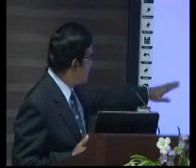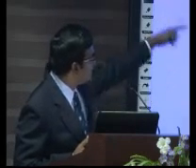What are the components in a skeleton bridge abutment? It has a base slab, with tapered columns on top of the base slab. Then you have the capping beam sitting on the two columns, and the wing wall, a very short, very small wing wall. So this is the three-dimensional view of the skeleton bridge abutment: base slab, two tapered columns, and the capping beam where the beams are sitting.